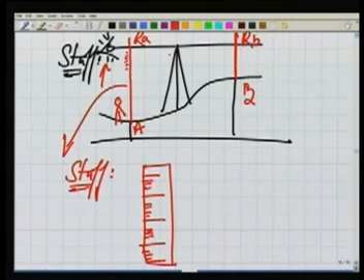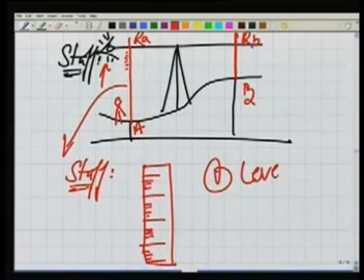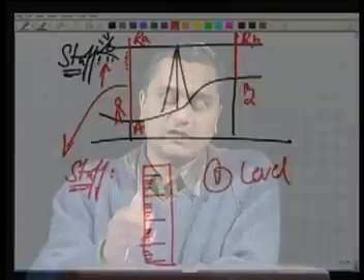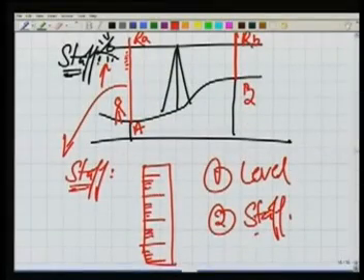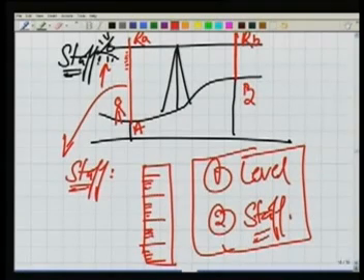So we are making use of now two things. Number one, level for making a horizontal line of sight, and number two, staff. And by making use of these two, we can determine the difference in RL of these two points or their relative height differences. We can find that difference.